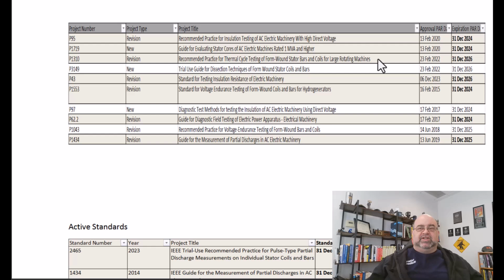4,500 horsepower synchronous machines that had 7-second startups had moved out to 11 to 14 seconds, things like that, because they were fighting that harmonic as they came up to speed whenever those machines were on. So I was the one who did the testing on the impact.